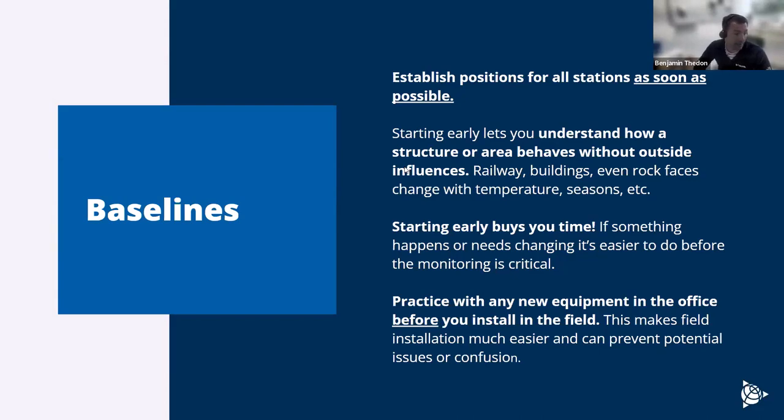Practice with any new equipment in the office before, and this is really key. Before you go on site, I always advise the customer to pair the sensor with a gateway already. So at least on site you just need to check the signal and you're sure it was working at the office, and it will prevent any potential issue or confusion.